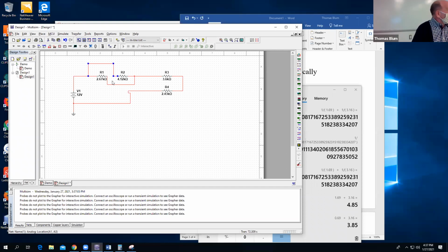Sometimes people will look and see R1 and R2 on the same level and say, oh, that's series. These are not in series, because series means the same current. Some charge will come out of 12 and come to this junction point, and some of it will go through R2, and some of it will go through R1, and then it will get back together.